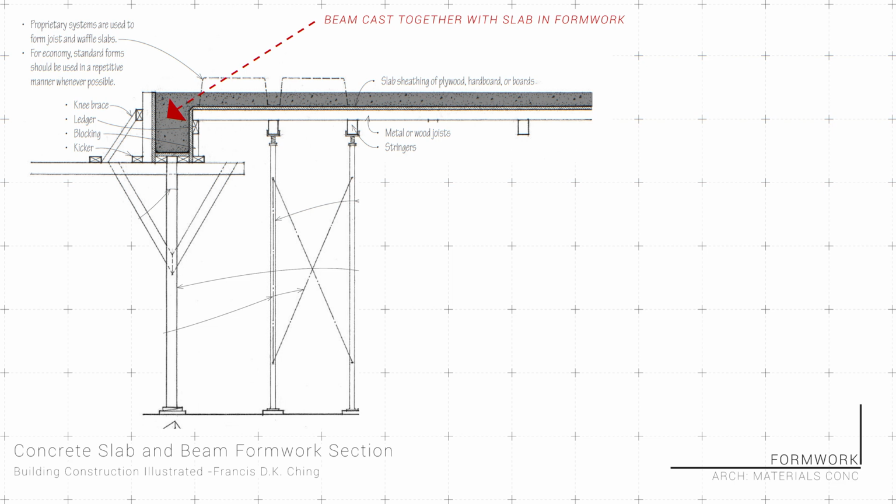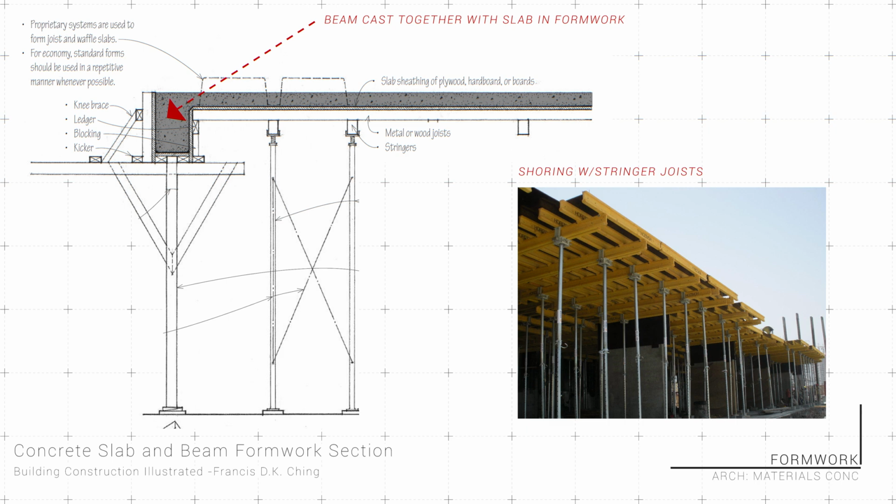On high-rises, where a floor slab and columns must be cast in stacks, we've got shoring techniques to hold up the slabs. These are temporary vertical columns that support joists, which hold an elevated floor slab as it dries. Shores can come in wood post formats or adjustable steel bars, not dissimilar to jacking up a car. Shoring is a common technique also used in all sorts of projects outside slab formworks, so they're quite common to see in all sorts of contexts.